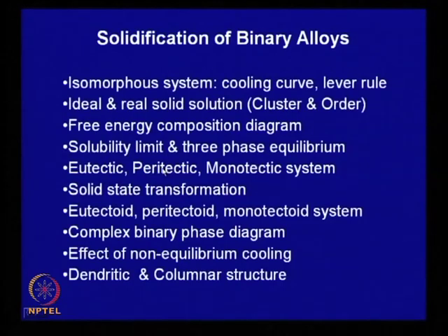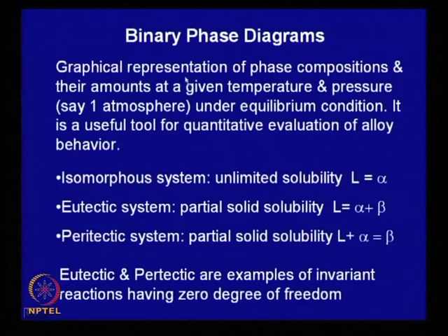Now, we will continue from here onwards. What we have seen is that the transformation that takes place during solidification of a binary alloy is represented in the form of a diagram, which is called a binary phase diagram. This is a graphical representation of phase compositions and their amounts at a given temperature, and often we do it at constant pressure, usually 1 atmosphere.